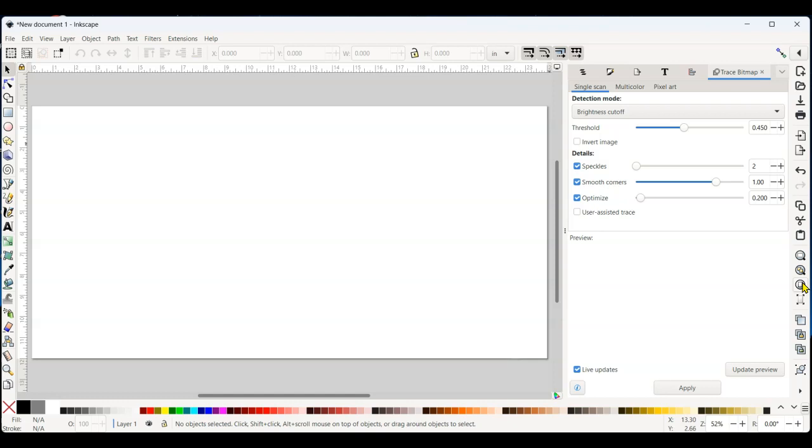And you'll have to design in the 12 by 24 workspace because sending it to the laser, it needs to know where you're placing the graphics. So it's always best to work in the upper left corner whenever you're creating graphics. At the end, once you're done, you can move it to the top left. But you can design anywhere on this workspace. Anything outside in the gray area won't be seen by the laser. So make sure that you're designing inside of the workspace, the white space that you see here.